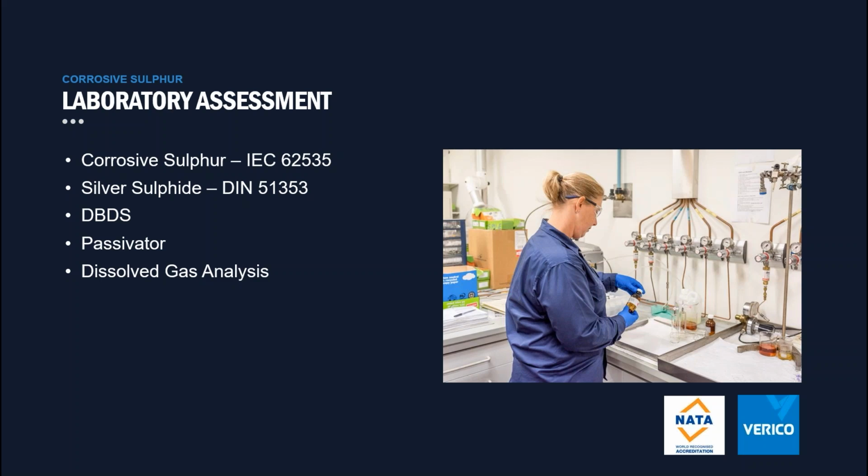So the DIN 51353 test looks at silver sulfide in transformer oil. So if the oil is corrosive to this test, it could spell problems for the silver contacts in the transformer and the tap changer. And also we might give you recommendations to evaluate the DBDS levels and also the passivator levels in the oil. We can also look at the dissolved gas analysis results to see if any heating is occurring in the main tank. So this may be being caused by corrosive sulfur deposits, and deposits of sulfides on bare copper and silver surfaces in the transformer can lead to increases in resistance and so overheating.